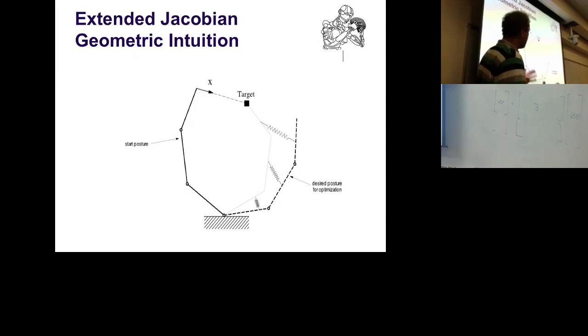So that's it. That was a quick step through inverse kinematic solutions. Small, important component: Jacobian transpose, super simple. It doesn't go straight to the goal, but it is very easy to do. All the other ones require matrix inversions and additional work and more linear algebra. In the end, it's not very hard to realize in like 30, 40 lines of code, depending on how you do this. If you use some math packages in C++, like Eigen or something like that, it's a very compact coding. If you write it in standard C with for loops, you just have nested loops for the matrix multiplications. It computes very fast.